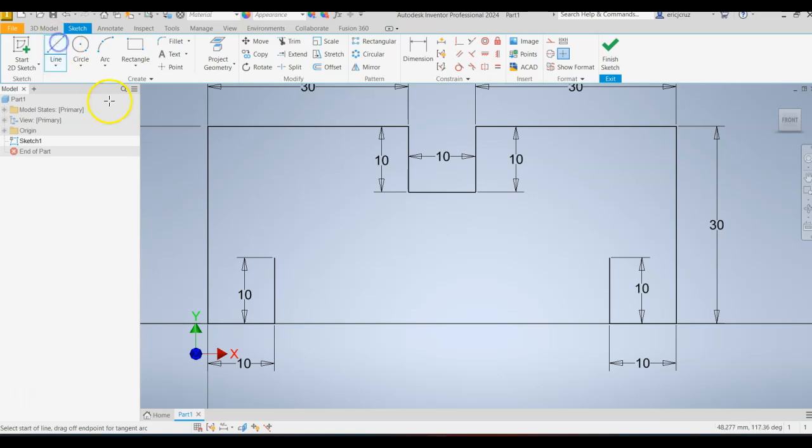So click on the line tool again, and where this ends right here, click, and we're going to go in this direction by 15. Oops, 15, and press enter, and then come back to this triangle right here, or to this point, and click, and then repeat, but do the opposite on the side.